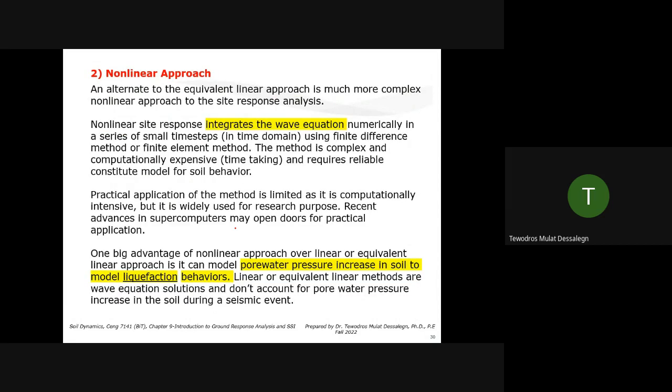The other approach is the nonlinear approach. That's where you use constitutive models. They are trying to model, at every instant, that high stress loop, like the Finn model I mentioned. But that's usually done in time domain, and they integrate the equations at every step, and they use very small delta t, something like 10 raised to minus 4, minus 5, minus 6. It's what's implemented in finite element and finite difference analysis in Plaxis and FLAC.